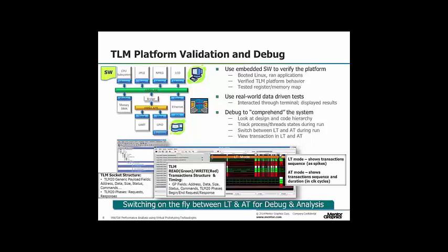Like I described before, we can capture data at certain points during the execution of the platform. So we can toggle between these two modes of simulation. And in fact here, the graphic displays a Linux boot. We're not interested in analysing the performance of the Linux boot. It's out of our hands, maybe. So we run the simulation in LT mode. Then at the point in time that we're ready to analyse our real applications that are going to run on the platform, we can toggle to the AT mode to start capturing the timing and power aspects of that.